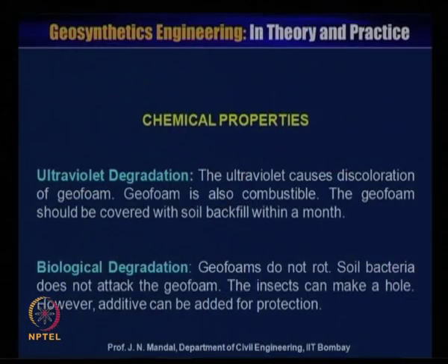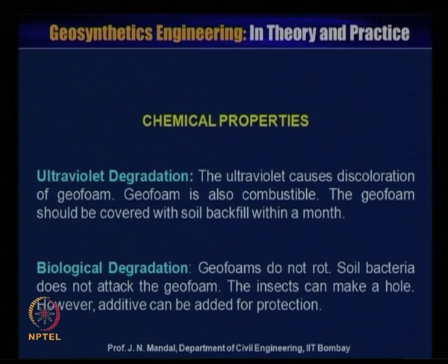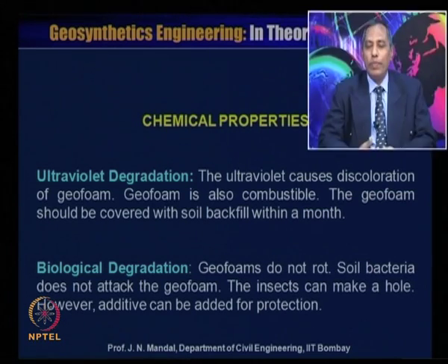Next, chemical properties. Ultraviolet degradation. The ultraviolet causes discoloration of the geofoam material. Geofoam is also combustible. The geofoam should be covered with soil backfill within a month. So, you cannot keep the geofoam material open in sunlight for a longer time, because there will be a problem from the UV light radiation or vandalism.